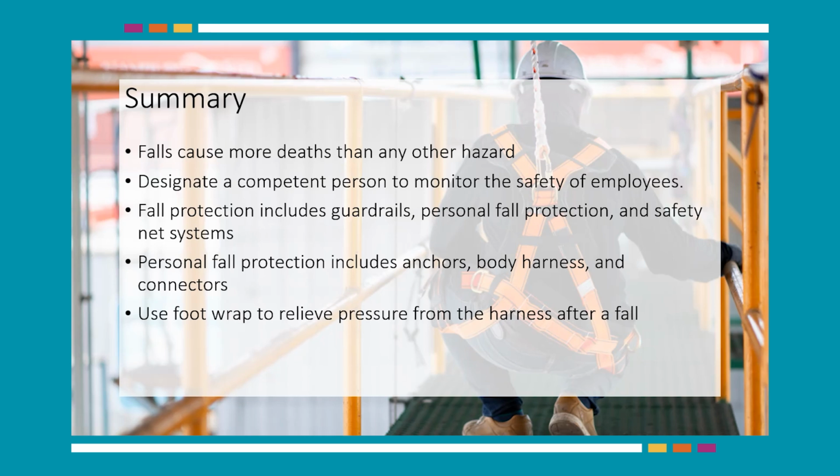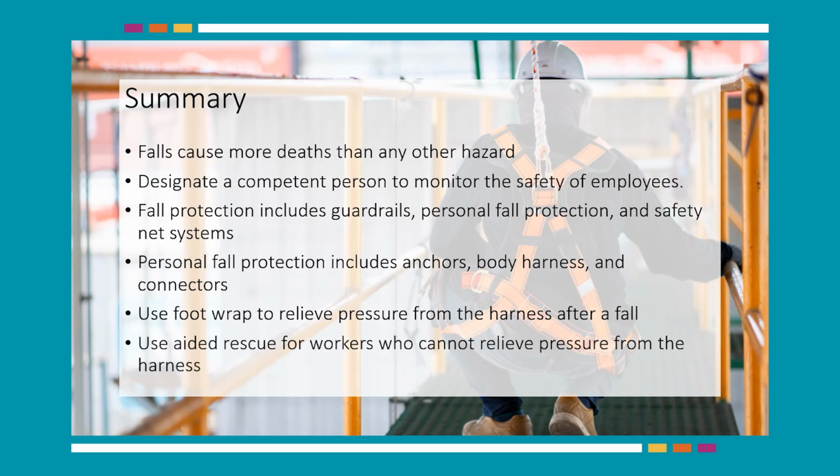In the event of a fall, use a foot wrap to relieve pressure from the body harness. If pressure cannot be relieved because the worker is unconscious or otherwise cannot perform a foot wrap, aided rescue is required.